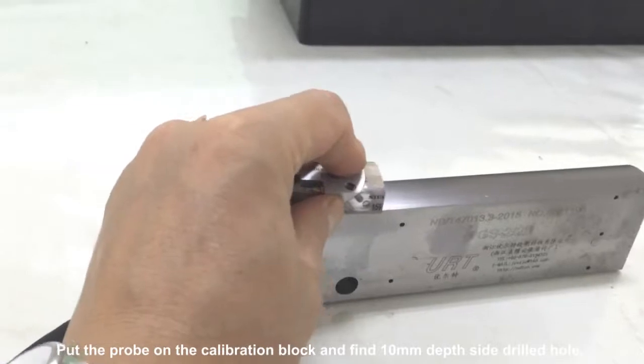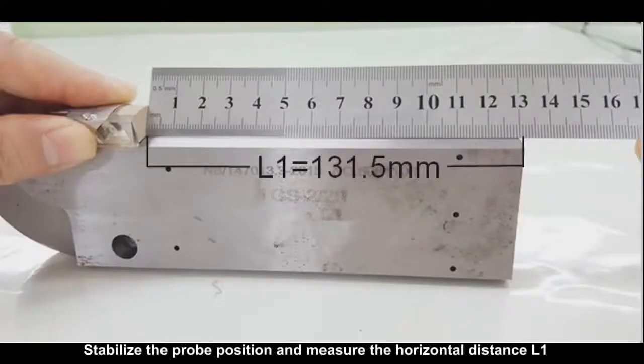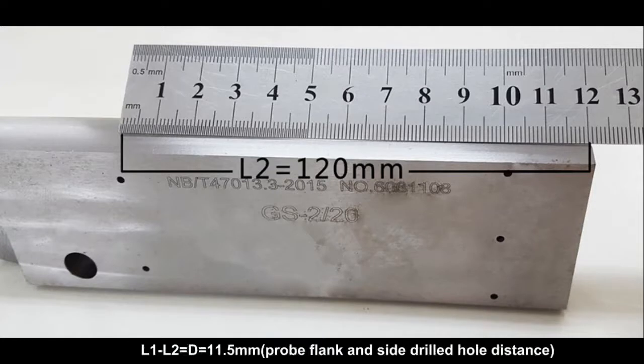Put the probe on the calibration block and find the 10 mm depth side drill hole. Stabilize the probe position and measure the horizontal distance L1 between the probe flank and the test block edge, and L2 between the side drill hole and the test block edge. L1 minus L2 equals D, the probe flank and side drill hole distance.